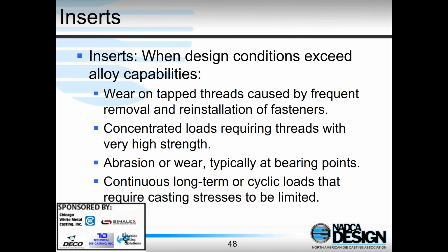So let's talk a little bit about if you're thinking about putting inserts into a die casting. When would you do this? Generally when you exceed the capabilities that the die cast material itself can handle. So if you have a bolted arrangement and you're worried maybe you'll strip threads on the die casting, or you've got an assembly that's continuously bolted or unbolted, then you can look at the use of inserts. And so inserts can help distribute the concentrated loads and also avoid abrasive wear.